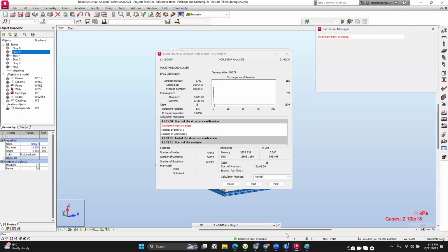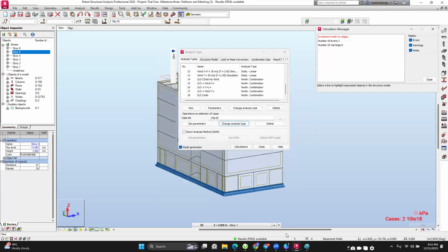The highest figure usually gives a factor of safety, so that in case the wind comes at the highest energy I'm expecting, my building will be safe. So it's not that you consider two directions at a go. It's one direction at a time, then you pick the highest value that you'll use in your analysis.